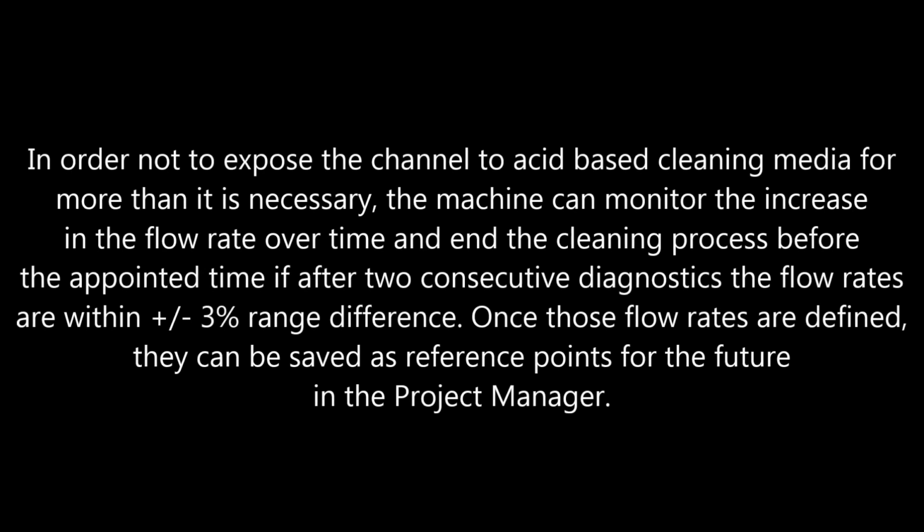In order not to expose the channel to acid-based cleaning media for more than it is necessary, the machine can monitor the increase in the flow rate over time and end the cleaning process before the appointed time if after 2 consecutive diagnostics the flow rates are within a ±3% range difference. Once those flow rates are defined, they can be saved as reference points for the future in the project manager.